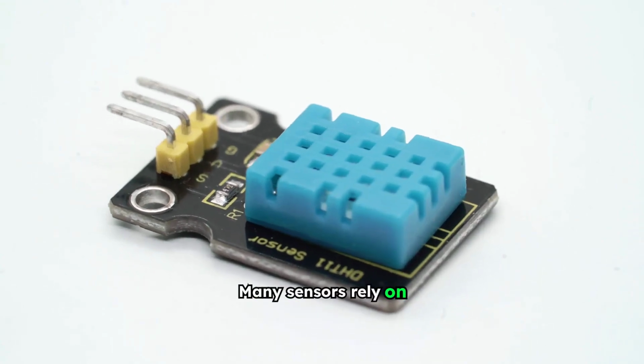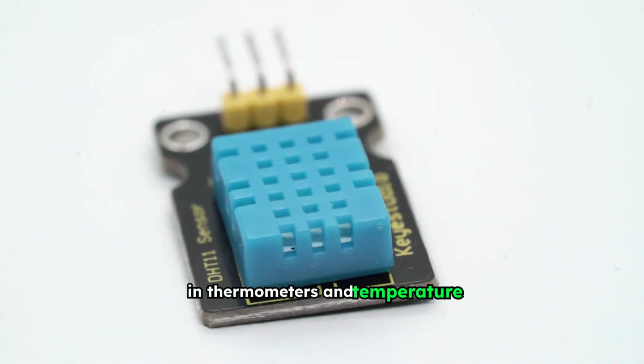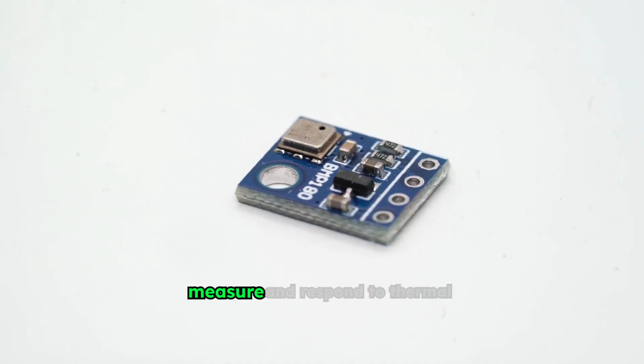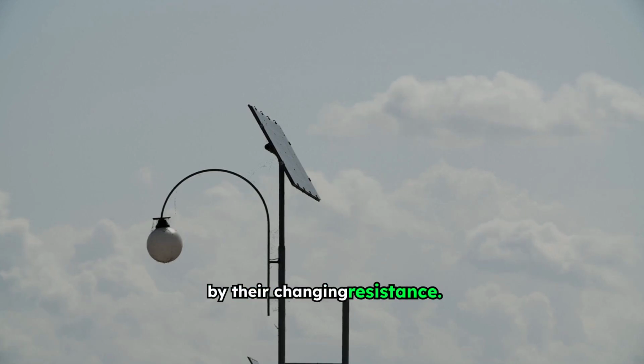Many sensors rely on changes in resistance. Thermistors, for instance, are used in thermometers and temperature control systems. Their resistance changes predictably with temperature, allowing electronic circuits to measure and respond to thermal variations. Similarly, LDRs are used in automatic streetlights, detecting ambient light levels by their changing resistance.